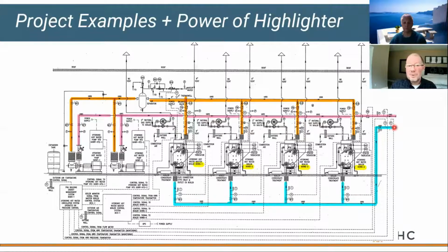Let's just look at this schematic real quick. First thing I'm always asking myself: primary, secondary, or primary only? So what am I chasing? Do I have dedicated pumps for each boiler? Do I have closely spaced T's, or do I have reverse return and motorized isolation valves?